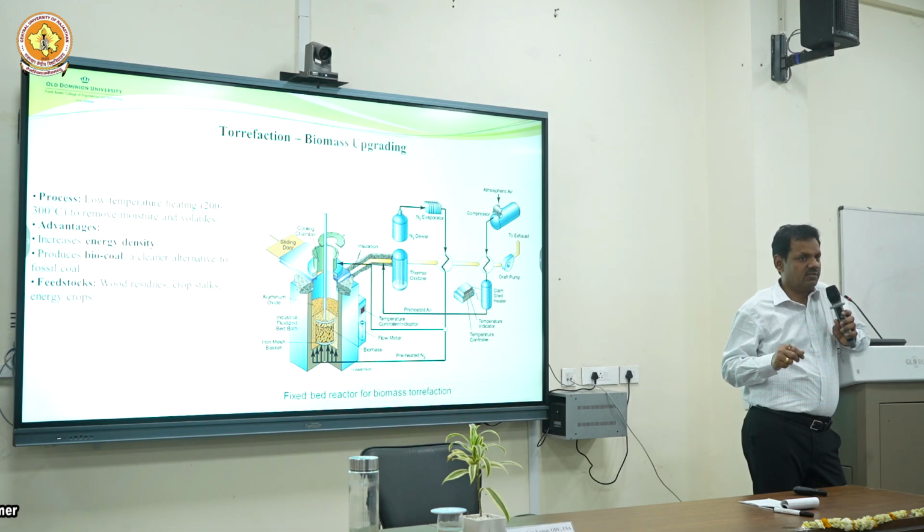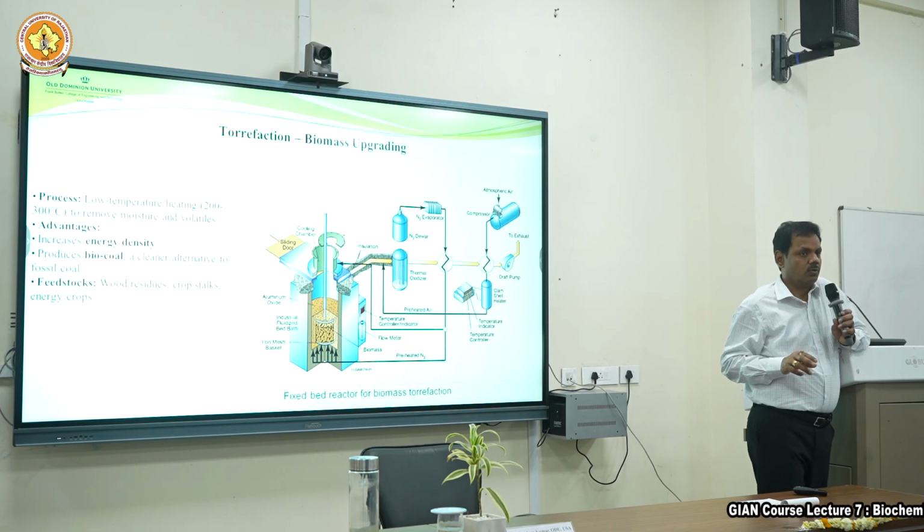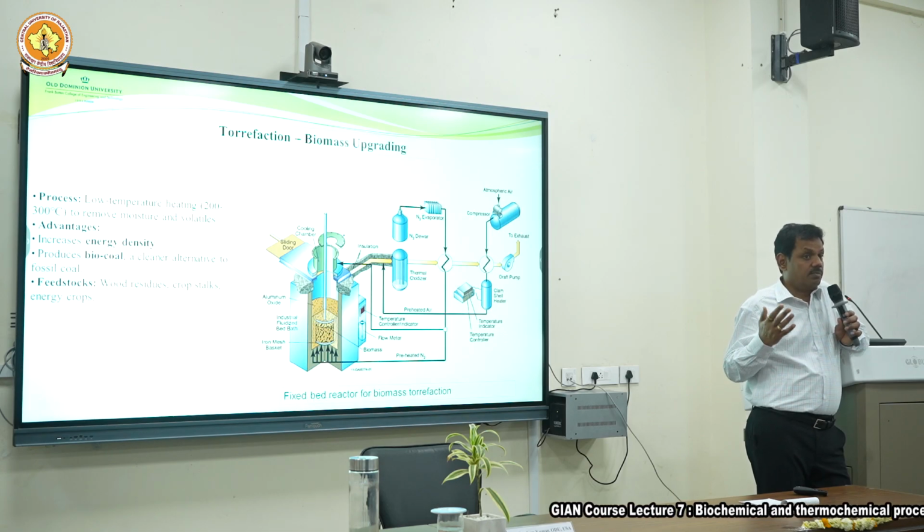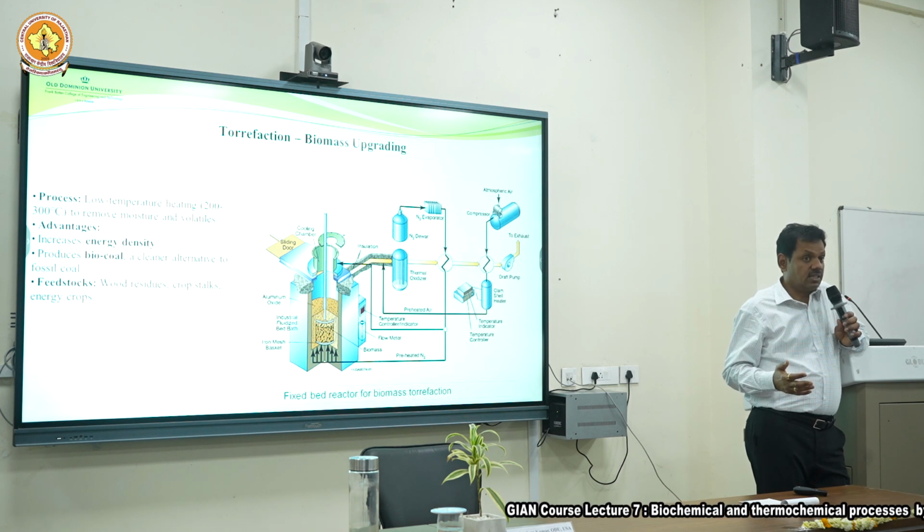Again, it's about energy, heating value, how much you are bringing. If you torrefy and pelletize, it will have more energy per unit volume. Okay? So torrefaction is roasting of biomass. It's like the coffee roasting we do. So basically roasting of biomass. Basically pyrolysis at very low temperature, 200 or something.